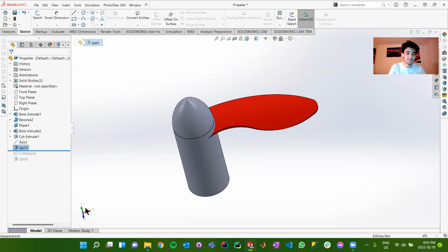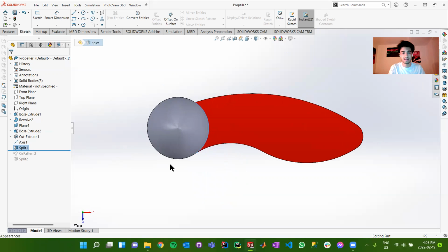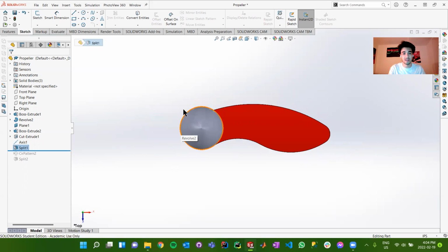Because if you can imagine, say if I were to look along the y-axis, if we were to mirror this shape about this sort of, I should say the x-plane, the plane where that is coincident along the z-axis, you'll notice that you would essentially get two different arches. So one, if you're following my mouse here, you essentially get the exact same shape, just flipped along the z-axis. So it'd look exactly identical, and this wouldn't actually be able to fly. So what you have to do is you have to implement a circular pattern instead.